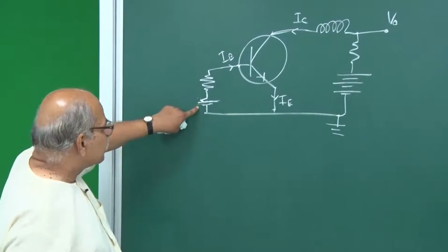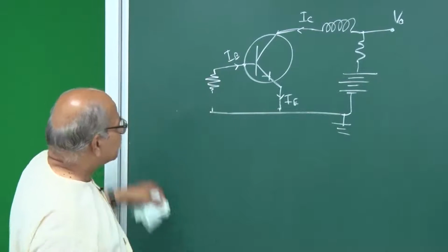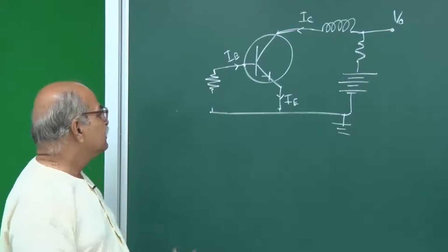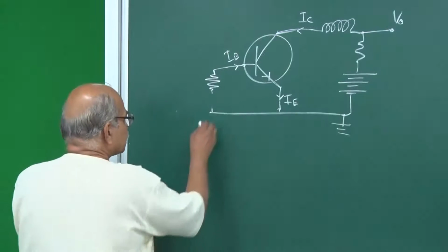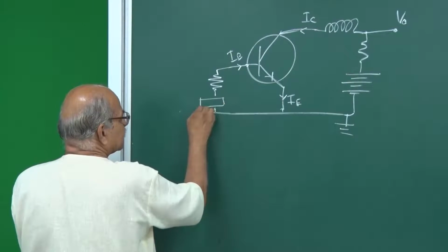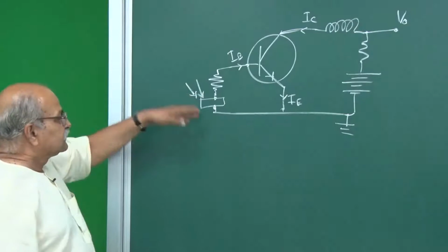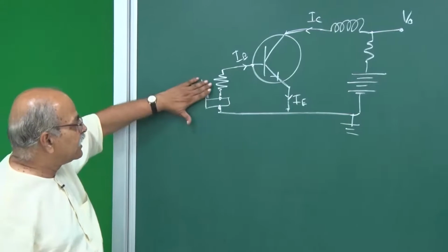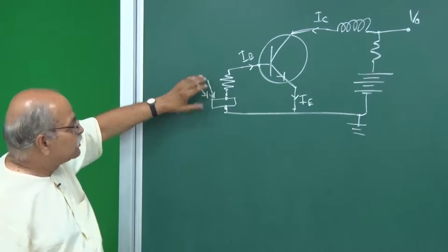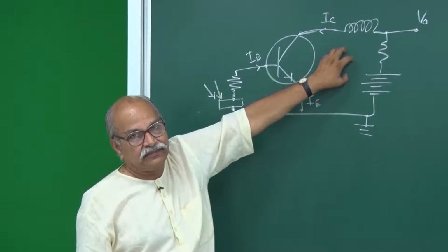Another interesting thing is you don't have to connect a real battery here. Any kind of voltage control which can drive this biasing from almost 0 to a large value, then you are done. So we will put a solar panel here. When light falls on it, the voltage is generated, and if this light is off, then there is no voltage here. So just by controlling the light here, you can control this part of the circuit.